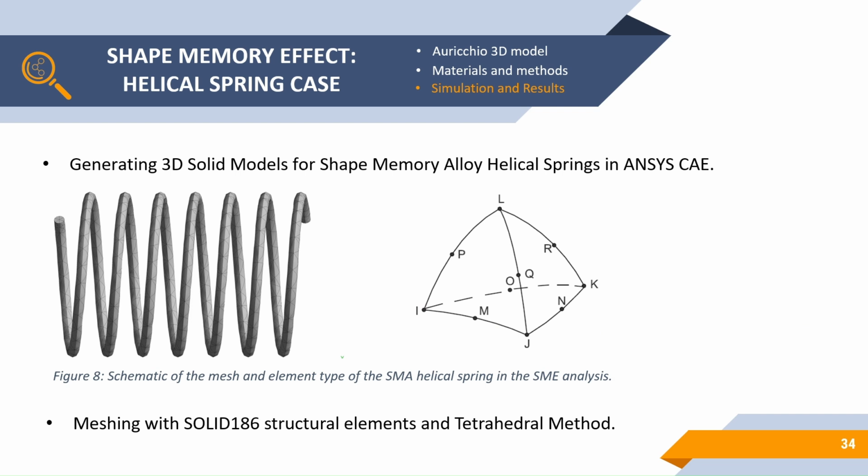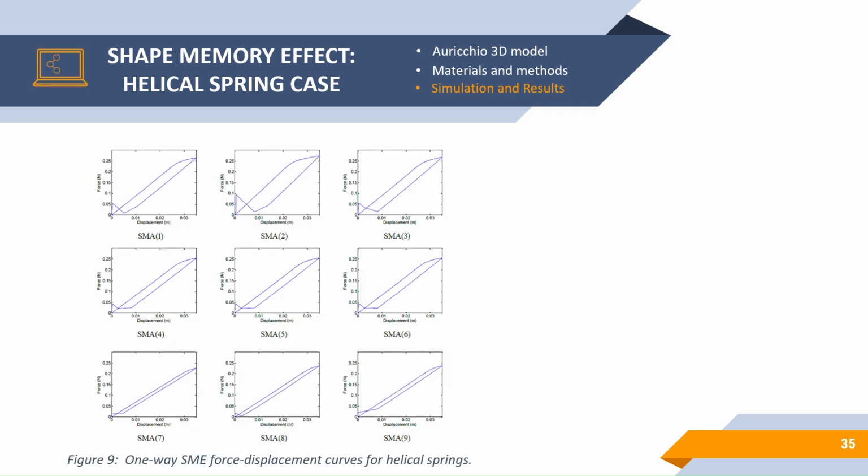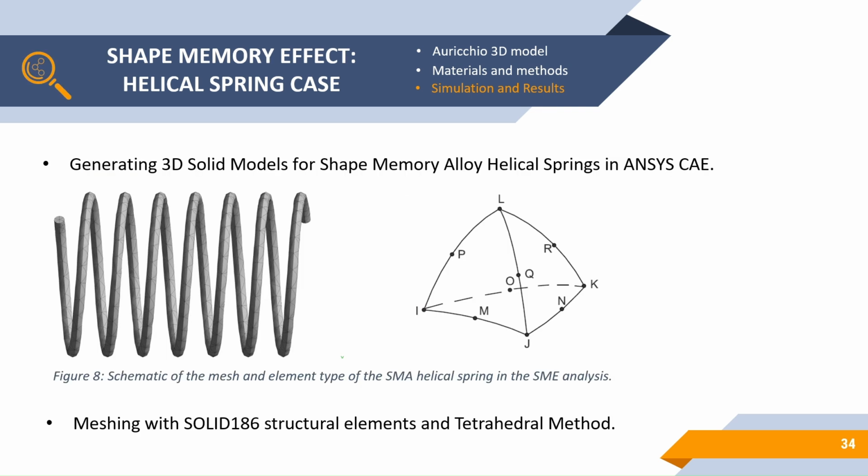The simulation of the shape memory effect of the helical spring was performed using a 3D solid model for each geometry, with meshing using SOLID186 structural elements and the tetrahedral method.